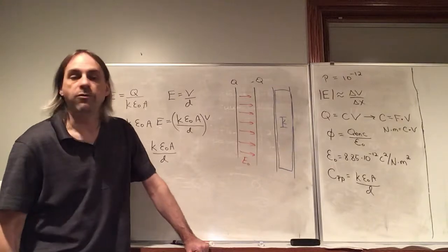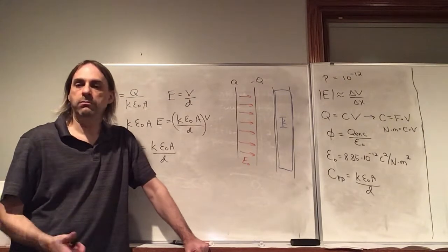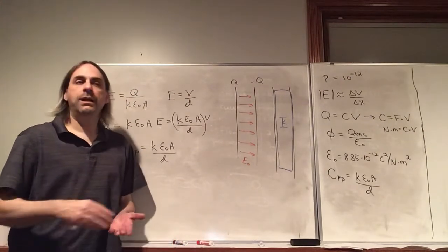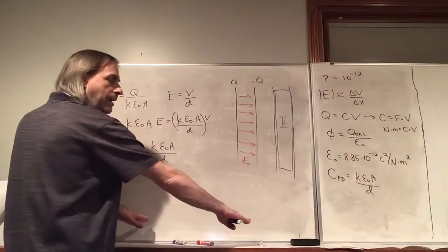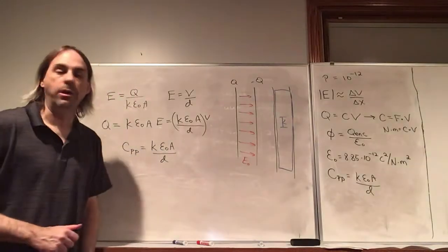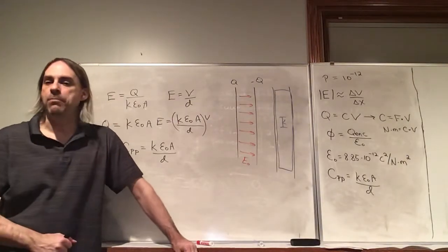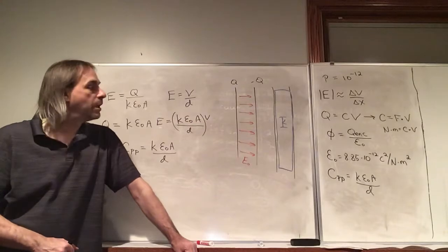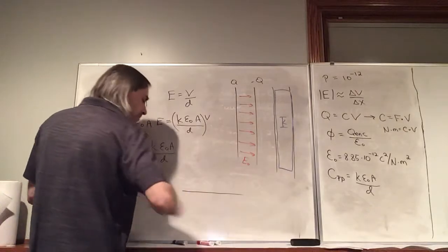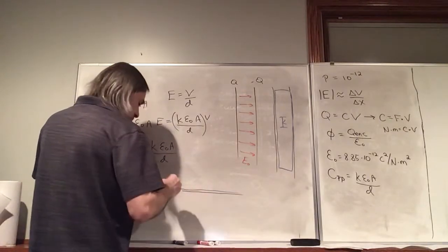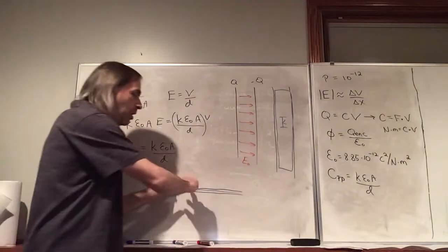And you need conductors, of course, to build any capacitor. So one conductor you could use is simply aluminum foil. And what's nice about that is it's flexible. So imagine you have a sheet of aluminum foil, and then you put an insulator on top and another sheet of aluminum foil. I mentioned that one of the dielectric constants is paper. You could simply use paper as your insulator or your dielectric. So you have aluminum foil, and then paper, and then aluminum foil. And you can have a long sheet of this.